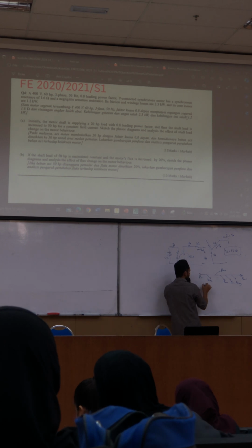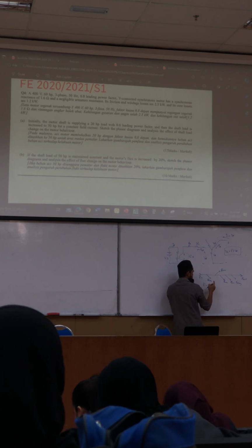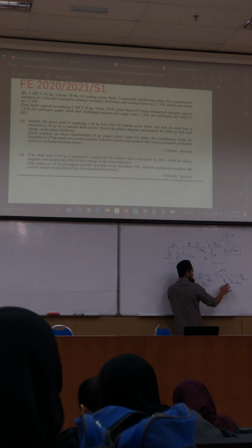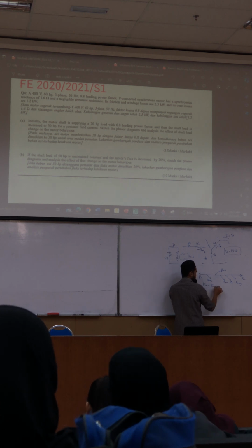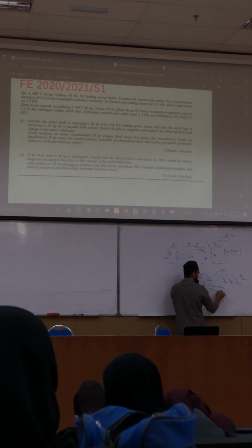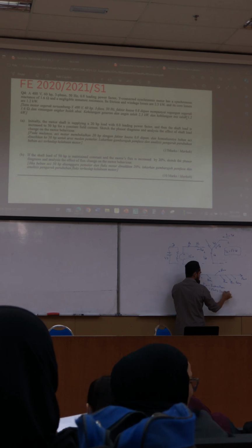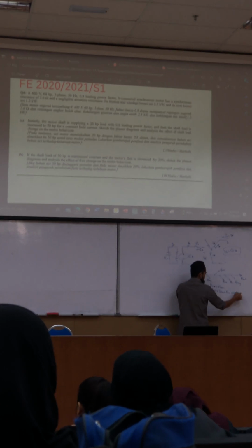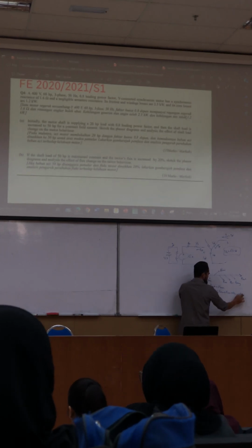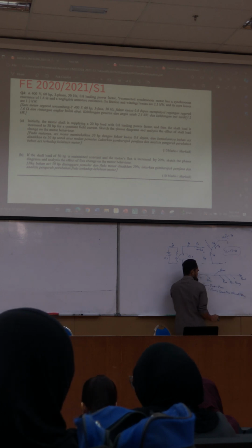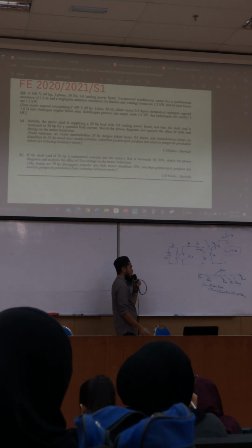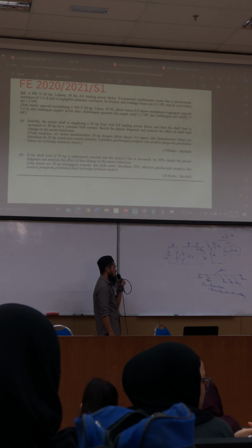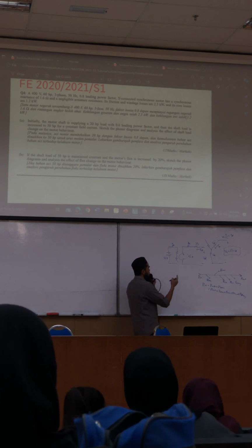Here we have P in, which is equal to P out plus all the losses. P out plus P losses, or P out plus P electrical plus P core plus P friction and windage plus P stray. So this is the equation that you can derive from the drawing or your sketch. So we talk about motor.